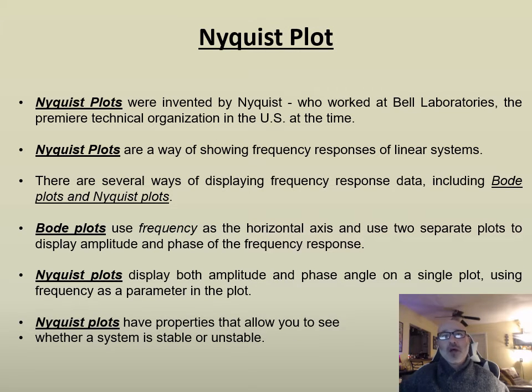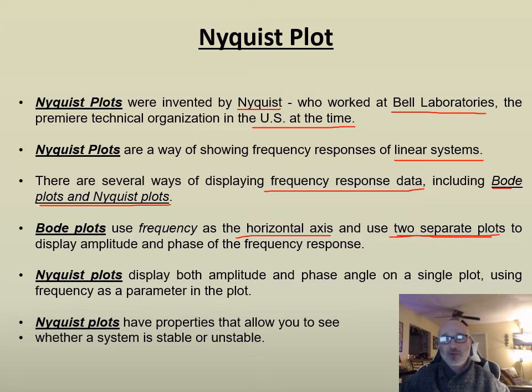These were invented by an employee at Bell Laboratories, Nyquist, which was the premier technical organization in the U.S. at that time. Now, these plots are a way for us to show frequency responses of linear systems. There are several different ways of displaying frequency response data, including, but not limited to, the Bode plots and our Nyquist plots here. Comparing those two, the Bode plots use frequency as the horizontal axis and use two separate plots,